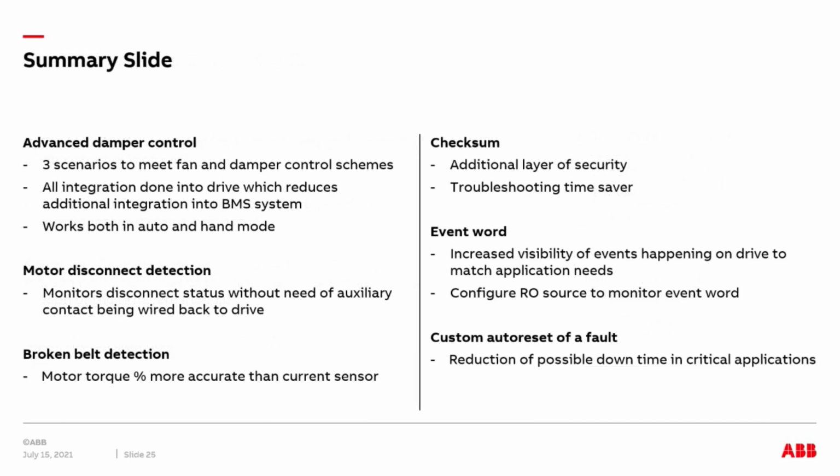Let's summarize everything we discussed today. First, we went over advanced damper control. We went over the three scenarios that are programmed into the drive that meet most damper control schemes in the industry. We also saw that with advanced damper control, we're able to integrate everything into the drive, which reduces additional integration into BMS systems. And we also saw that this works in both auto and hand modes.